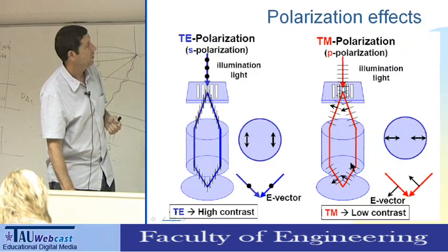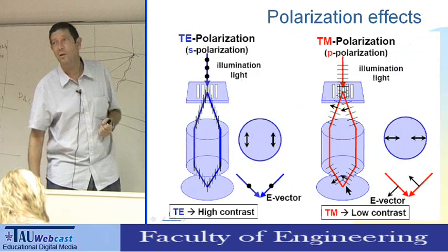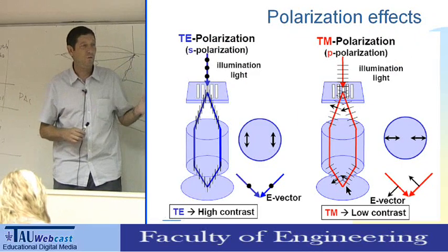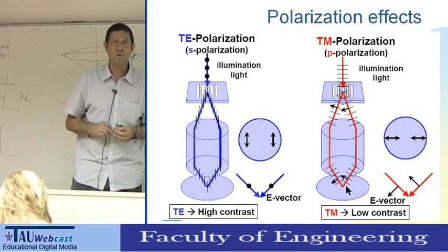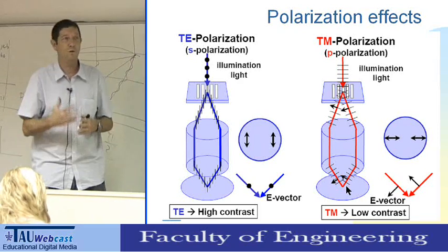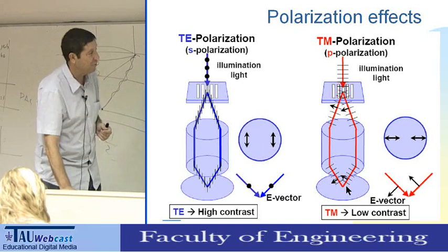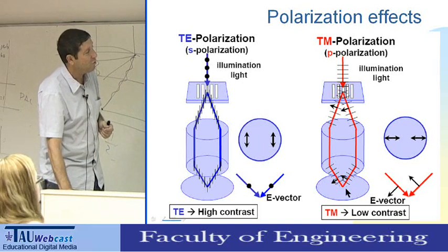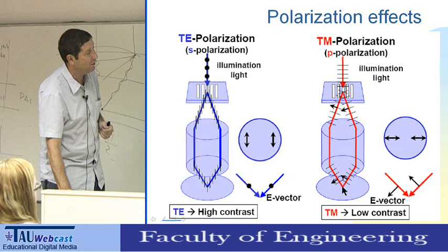Different index for magnetic and electric? Yes. So actually, it's a very good comment. This effect of polarization, when you do immersion lithography, is more pronounced because of the refractive index of the water and the effect on the actual electric field when it hits the substrate.